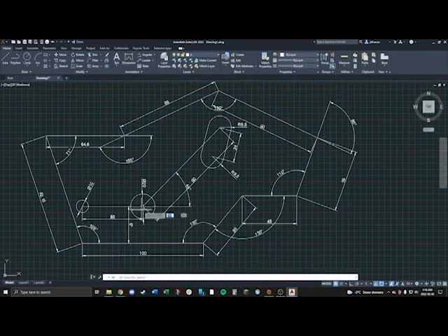So any lines that are supposed to be 0, you want to hover over the intersection and double check that the numbers are whole numbers. It doesn't work on anything with an angle, but if it is supposed to be a straight line of 0, a lot of times it's really tempting to just click enter when it's hovering over the 0. That could be off by a fraction of a degree. I lost a lot of marks on the last project doing that. Just make sure that it's 0, and if not, go back and change everything that's based off that, and make sure everything's correct. It'll save you a lot of time and get you a lot more marks.